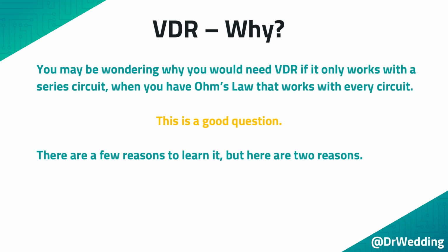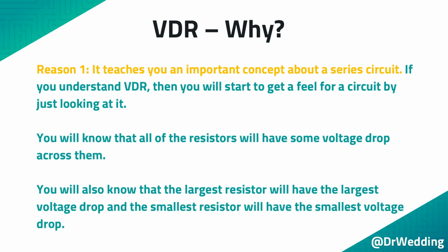You may be wondering why you would need the voltage divider rule if it only works with a series circuit, when you have Ohm's law that works with every circuit. This is a good question. There are a few reasons to learn it, but here are 2 reasons. Reason 1. It teaches you an important concept about a series circuit. If you understand the voltage divider rule, then you will start to get a feel for a circuit by just looking at it. You will know that all of the resistors will have some voltage drop across them. You will also know that the largest resistor will have the largest voltage drop, and the smallest resistor will have the smallest voltage drop.